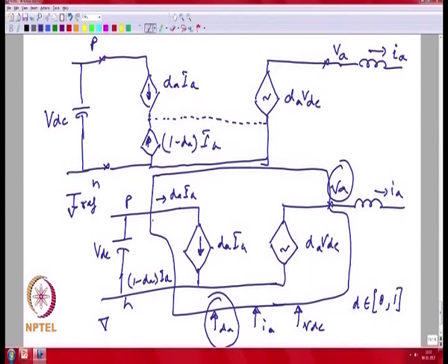Okay. But if you look at it from the reverse perspective, where you are looking at the currents that are coming into your DC bus, your duty cycle might be a sinusoidal quantity, your input current would be a sinusoidal quantity. So you may not be able to take a simple gain model as the relationship between your currents at the input and output. One current might be 50 hertz, and then your ripple now on your DC bus is starting to occur at 100 hertz, etc. However, between your duty cycle and your output voltage, you have the same frequency effect, so you could consider it to be just a linear amplifier with simplifying assumptions regarding the DC bus.